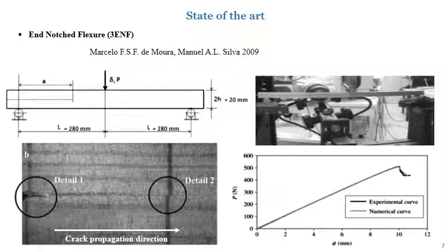24 specimens were machined and conditioned at 20 degrees Celsius and 65% relative humidity until equilibrium was reached, resulting in a moisture content of 12% in the wood. The average specific gravity was 0.55. The initial crack was introduced in two stages. Initially, a notch was machined with a band saw 1 mm to 2 mm thick. Then, the notch was extended using a cutting blade and taking care not to apply a large load during the operation. The initial length of the crack, which is a fundamental parameter, is said to be accurately measured.